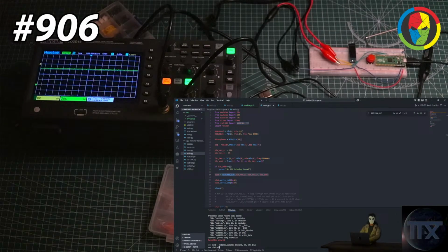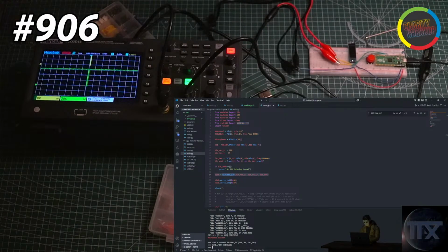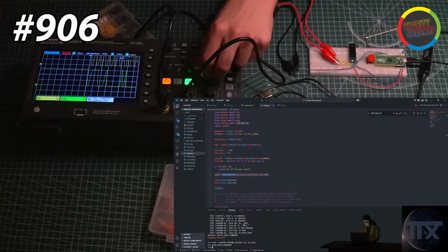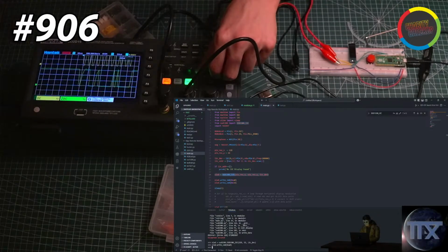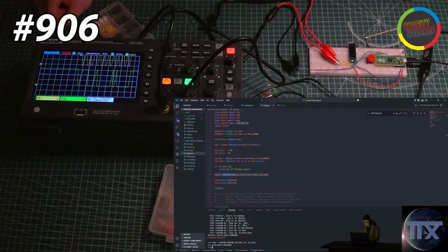Okay. Now what I can do is write a simple command to the OLED, like this. Oh, there we go. So not much information there. Yeah, and if we zoom in, we could reverse engineer it, couldn't we? Yep, you can. Another interesting thing: it makes a lot of sense, I just never thought about it. The clock only activates for the data. If there is no data, then there is no clock. That's curious. It's almost like a trigger.